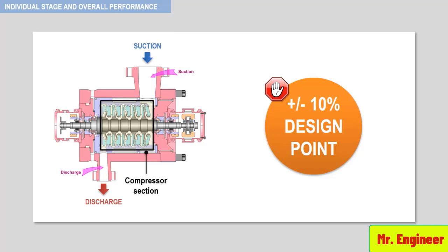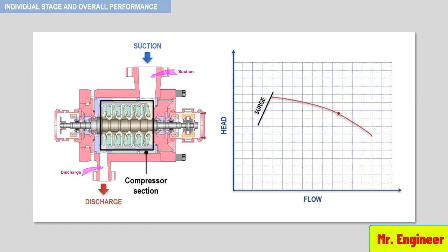The resulting section operating curve can deteriorate in a significant way in terms of head, flow range, and efficiency. Another case that we will consider in this section is the change in gas molecular weight. Remember that once an impeller is designed, its energy production or its head production at a given flow point is essentially fixed. We will see that pressure rise will change as gas composition changes.